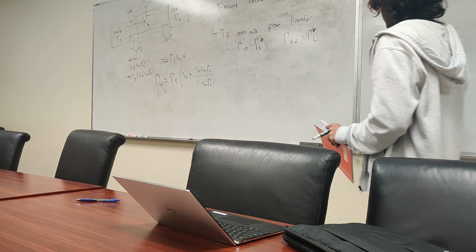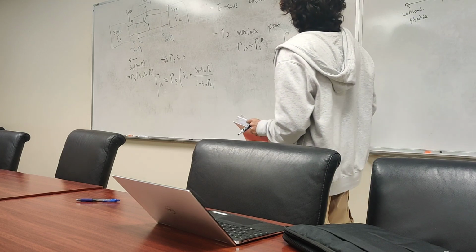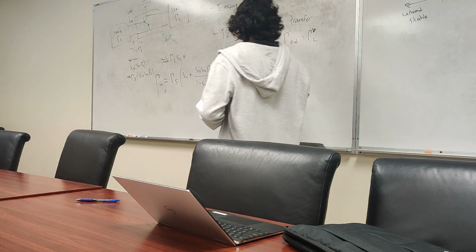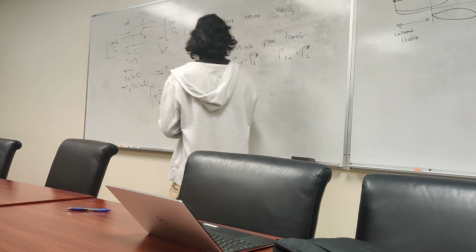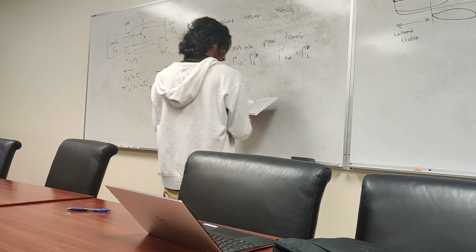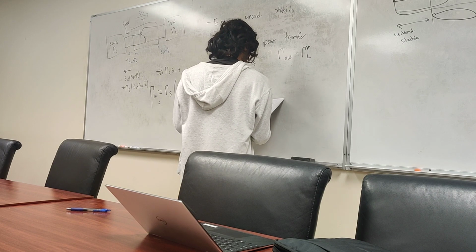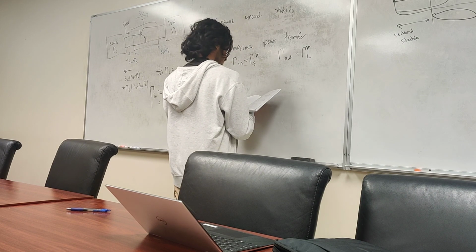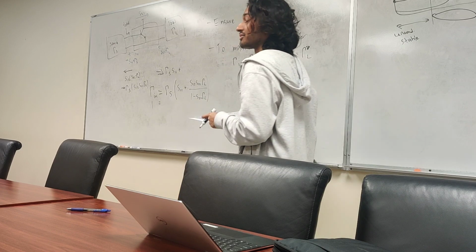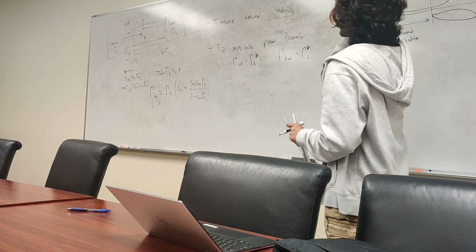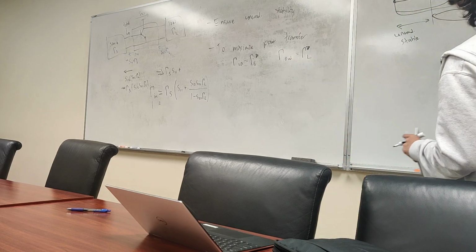I mean, there's a little approximation made there, in reality, no. But for BJTs, yeah. For transistors that have a low S12, that are unilateral, you could do it. So we can still go for maximum gain. And usually software can do all this for us, which is really nice. We don't have to do any of this math, we don't have to do any of these circuits.